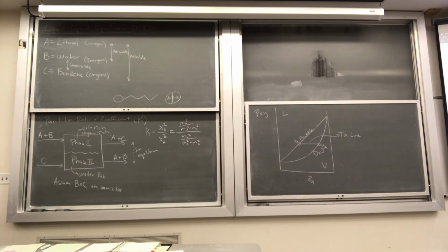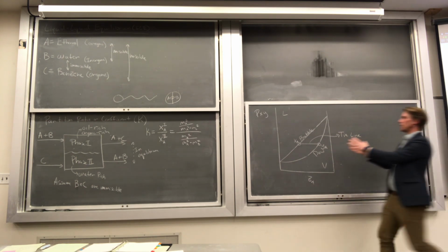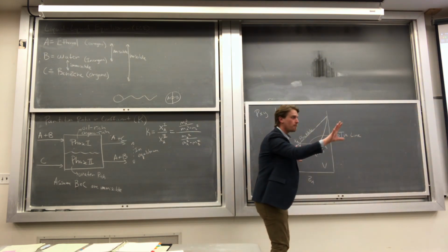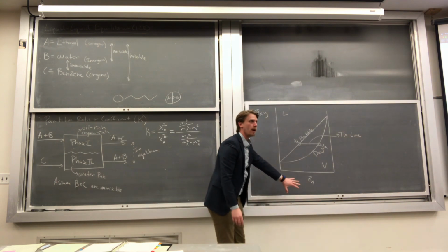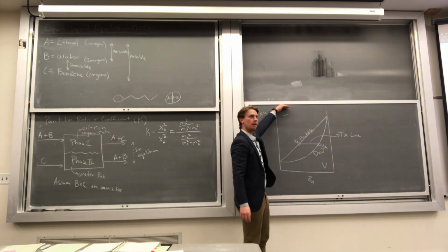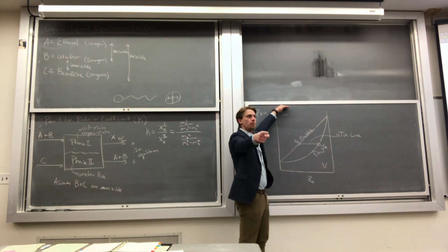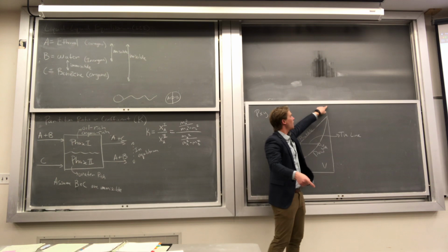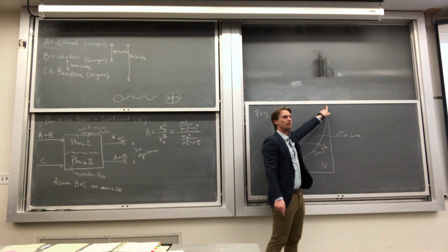The phase boundary, is that like? That's this curved region right here, which is the same as this curved region here. So, for example, in this PXY diagram, if I pressurize my system to here, my fluids are now miscible. From here to there, I never cross a phase boundary. Miscible.